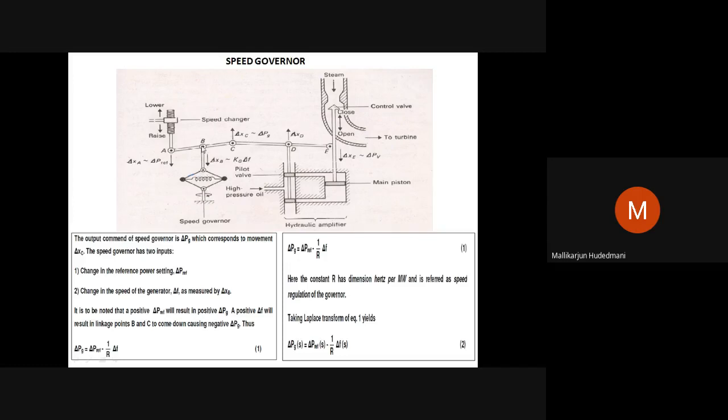Once there is a reduction, this point will be lowered down. This will be pulled down. Not pulled down, it will be raised up, because when there is a whirl effect, when I have a stone and thread rotating around, definitely it comes down. It comes down means vertically it elongates. These two points vertically elongate whenever there is a reduction in speed, and these two will come down, horizontally elongate, when there is a high speed. So this way I can change the valve open-close condition depending upon the speed feedback of the actual turbine, which will be reflecting on the particular valve.